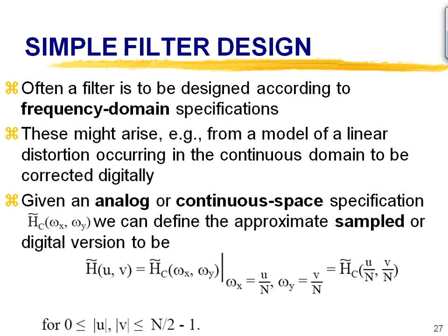And I want to operate on this image with a filter whose properties are that it cuts off all frequencies greater than, let's say, 25 cycles per image. Okay. So, well, that would be an easy filter for it to design, right? All I would need is to say that, well, in the Fourier domain, give me an isotropic filter, right, a circle, so that it basically cuts off frequencies equally in all directions.